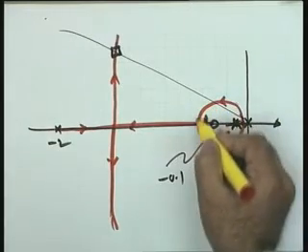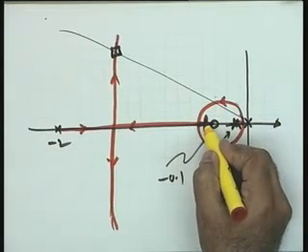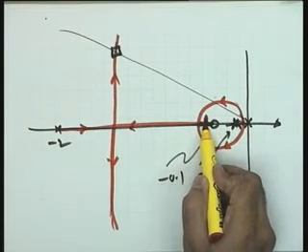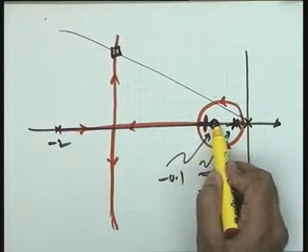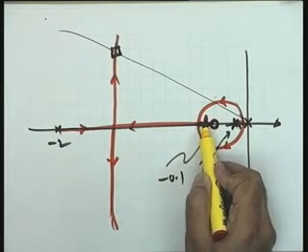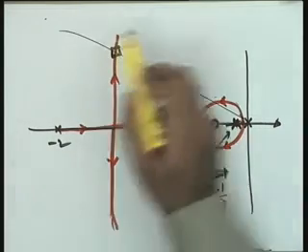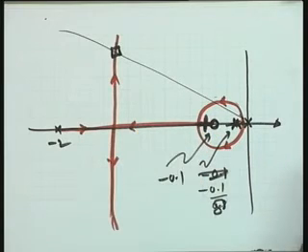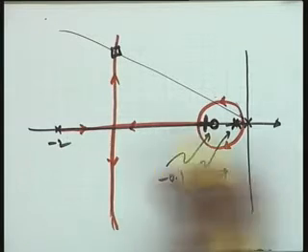The real pole for this value of K is going to lie in this particular region, and since the third pole is in this particular region, there is a 0 close by, and hence this 0 is going to nullify the effect of the third pole, and hence the dominance condition is more or less satisfied, though the third pole is quite close to the imaginary axis. The dominance condition is satisfied, and hence this is the clue only.